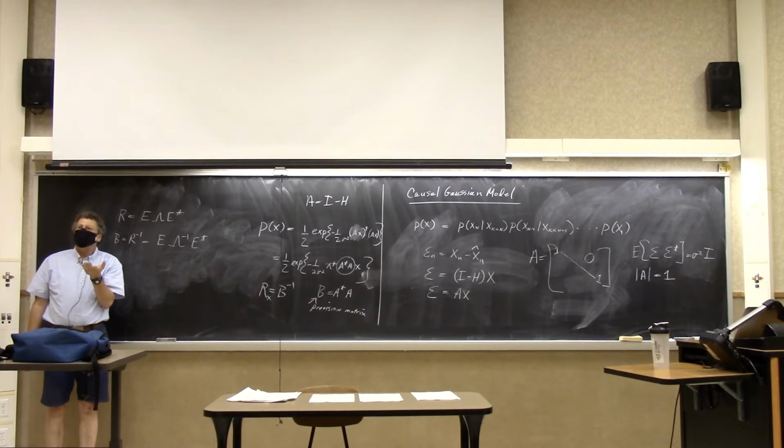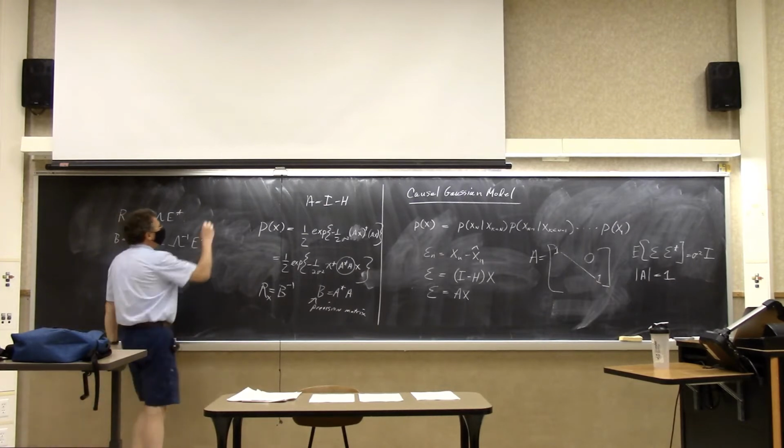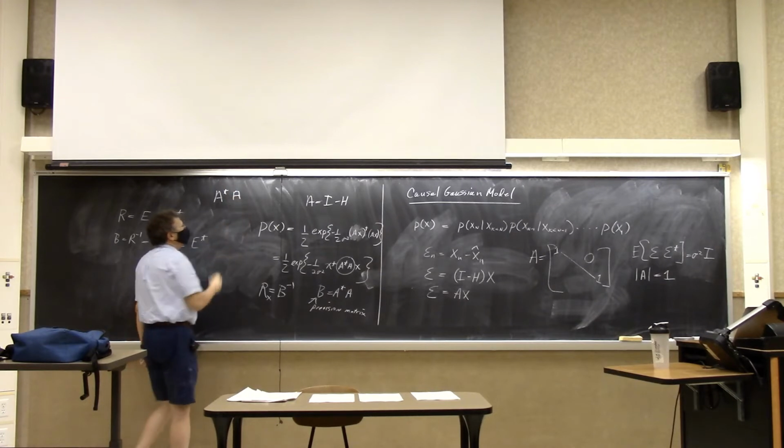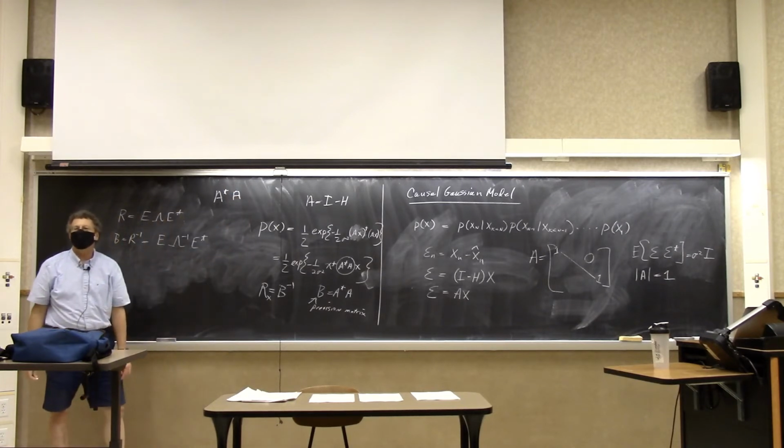If you have a radar or communications background, there's this thing called a matched filter. How many people have heard of a matched filter? Okay, good. A matched filter is the transpose operator. The assumption is that you send the signal out, and then to decode it, you use the matched filter. So there's a sense that it's the inverse, but it's not the inverse. It's just the matched filter. The idea is that for a randomish matrix, A transpose times A tends to approximate a scaled identity, okay?